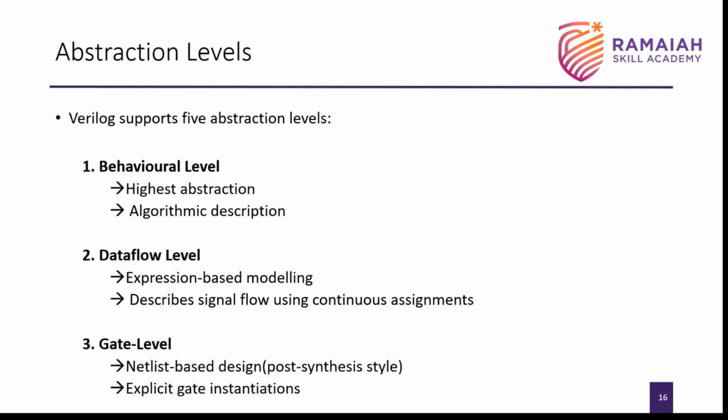Okay, so behavioral level discusses that. Data flow, how the data flows from input to output or from one block to another block. Okay, it's a very simple way of writing the code in data flow level compared to other abstraction levels. Gate level, in other words, deals with the logic gates. Okay, netlist is nothing but the logic gates. This deals with the specific types of gates and how the gates are connected.